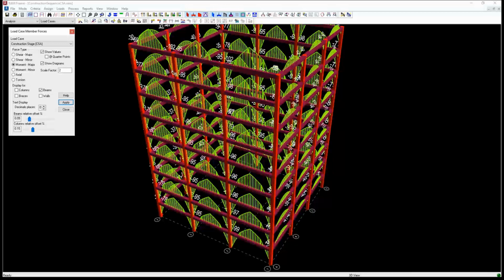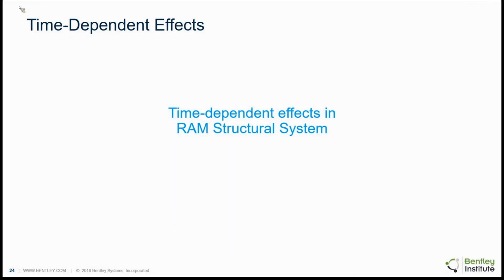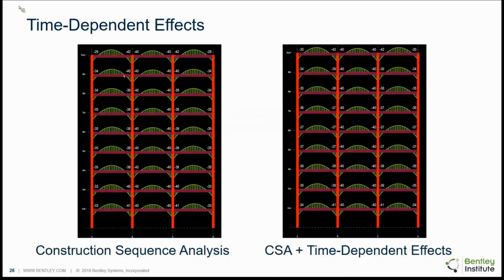So I want to express right now how easy it was to take these effects into account merely by setting up that information and setting up that load case as I indicated. So it's merely that simple. So I grabbed those results first of just the construction sequence analysis by itself, and then the analysis that we just did where it includes the time-dependent effects, and we can see those side by side.